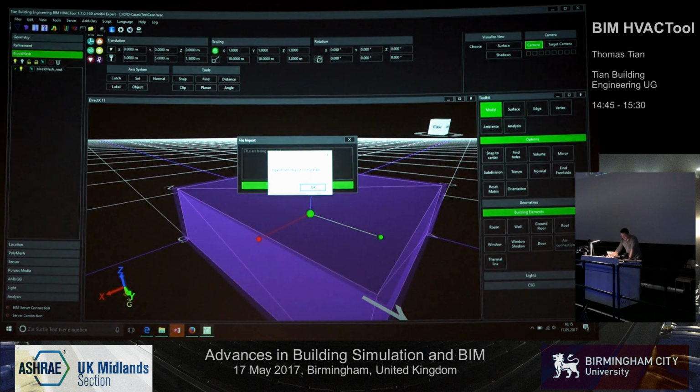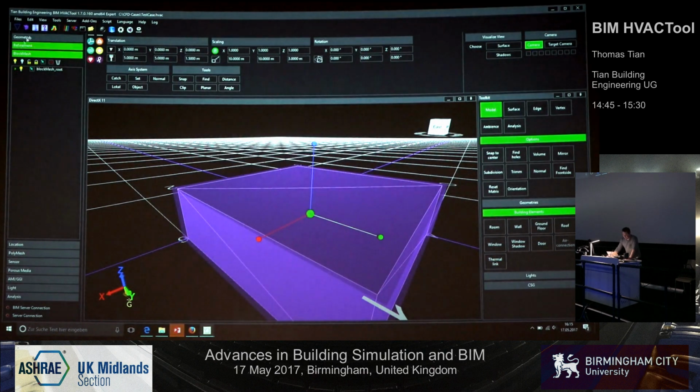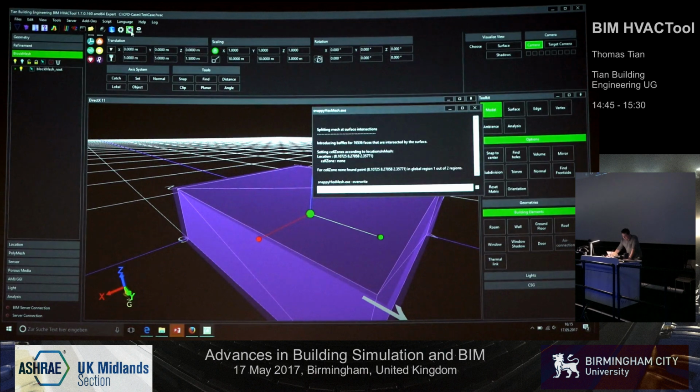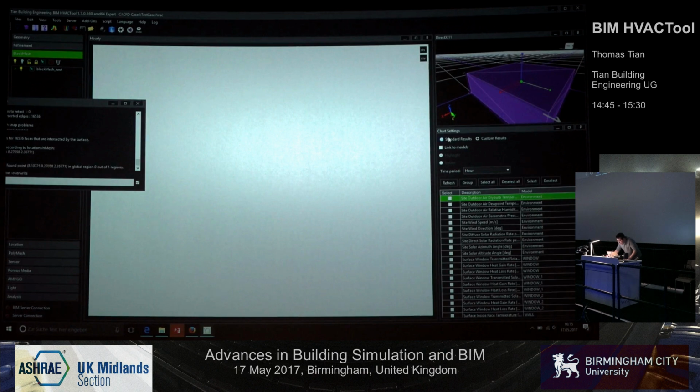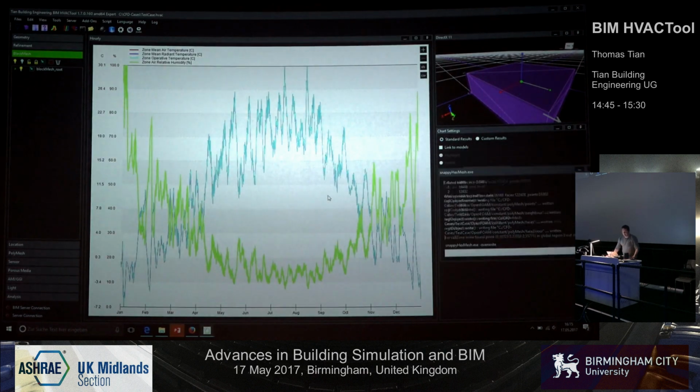Okay, again, block mesh. We create a background mesh for OpenFOAM, and snappyHexMesh is a powerful meshing tool. You can handle complex buildings. You do not have to take care like 20 years ago. You can only take your 3D model and push it to OpenFOAM, and snappyHexMesh does the rest. And in OpenFOAM, you can go to results, and then we need some standards, and whatever temperature, and then you have the result. But I think that's not new for you.